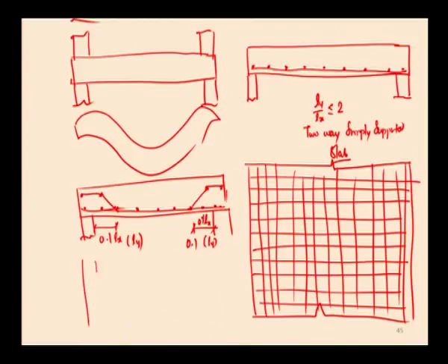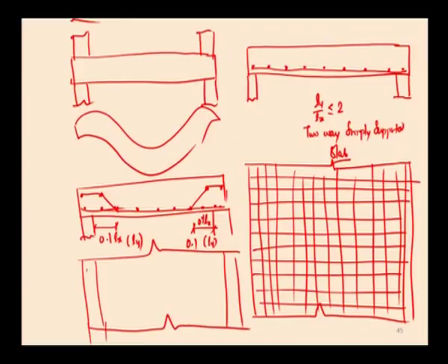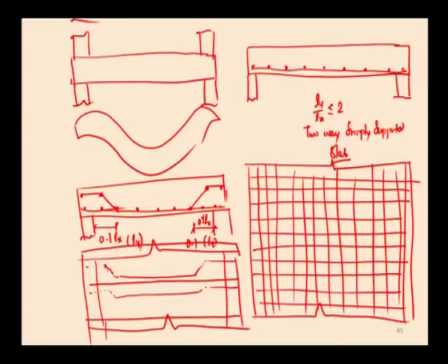So, here in the plan view, this is a support. This is the arrangement of the reinforcement. This is another bar, a straight bar, and this one is the cranked bar, and here you are having the wall. You assume that here we are having the wall. This is the straight bar. In this direction also we need to provide the main reinforcement.